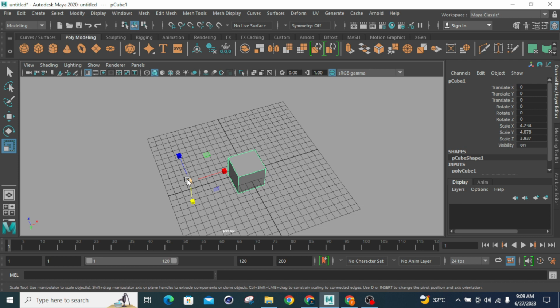Before going to snap to grid, if we press W, first I have to delocate it. If you press W, we can move the value, or we can move the shape with my shortcut, which is my W. W is used to move the shape. Again, to snap to grid, first I have to go with the snap to my vertex. So first I have to go with V.